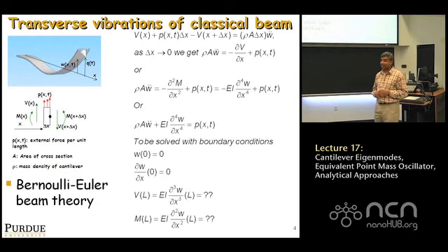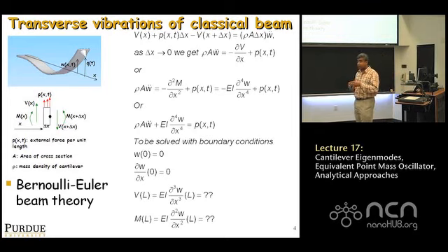It is a slightly tricky question, because after all, this entire equation of motion I wrote down was for the beam, not for the tip, right? So if we want to include the effect of the tip, in some sense, it would have to come into the boundary conditions at x equal to L. Because so far the equation is just for a beam, not for a little sharp conical tip at the end. So if you just set this equal to 0 on the right-hand side, you're basically saying that the mass of the tip is negligible, right?